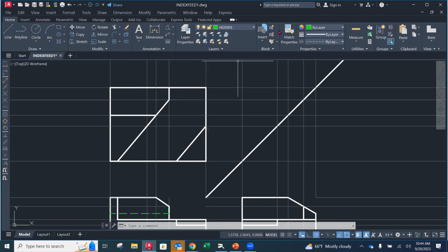I got a chat: 1.625. Thank you, Caleb. So now we're going to snap from this corner right here in that top view. That's going to be our base position, like our 0,0 for this command. And we're going to say at 1.625 and then up 0.75, so that our X dimension is 1.625.